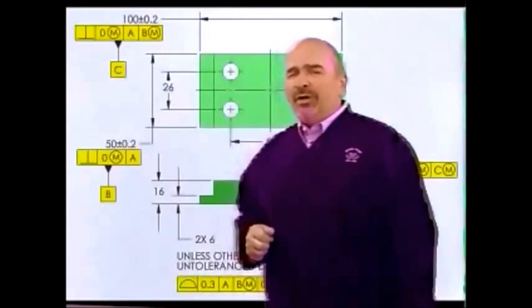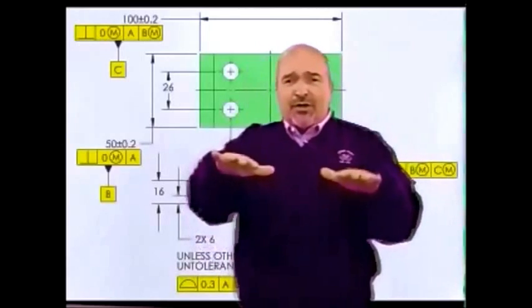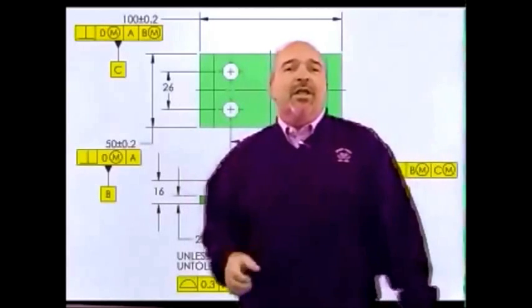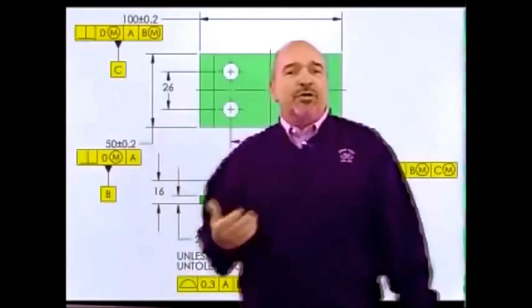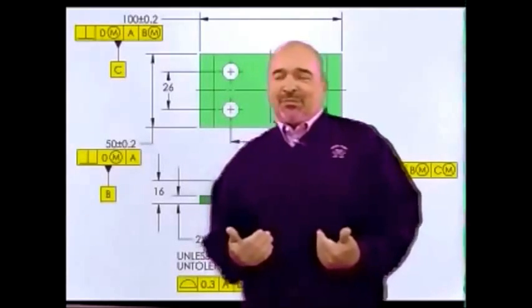The math standard, Y14.5.1, clears things up a little bit. It says, yes, there is an infinite number of planes there. They're called the candidate datum set. And you are allowed as an inspector to pick the one that will bring the part into tolerance.